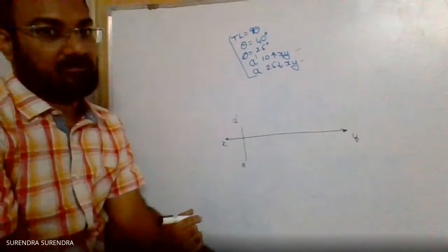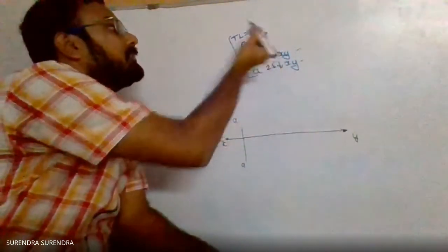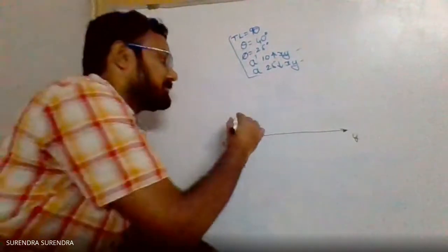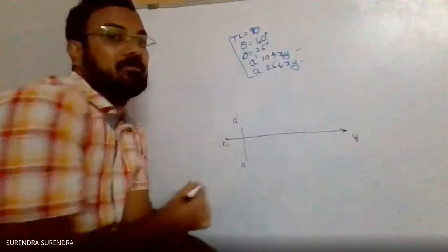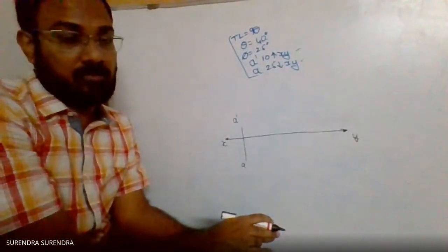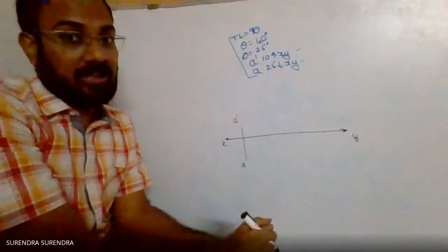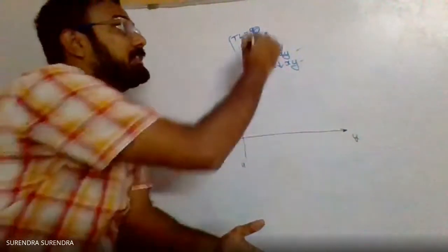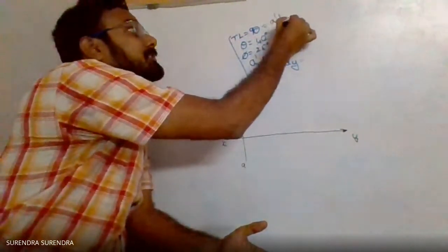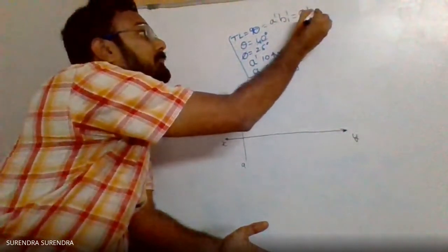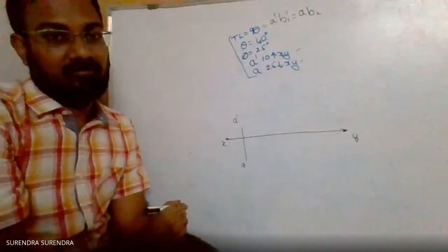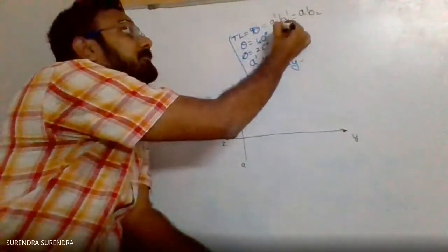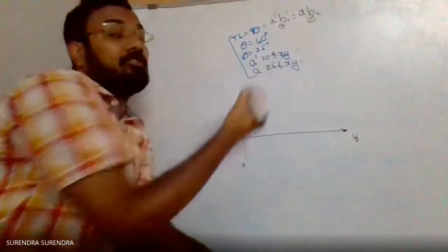Next, the line is inclined to the horizontal plane at an angle of 40 degrees. So the horizontal plane inclination first, with 40 degrees inclination. Just note the points, as I said just now. The true length of the line is nothing but A dash B1 dash, also equal to A B2. A dash B1 dash is inclined at theta to HP, the XY line, and A B2 is inclined at phi with the XY line.